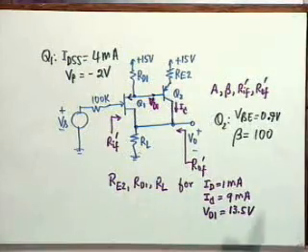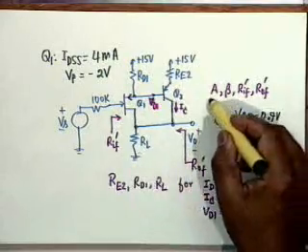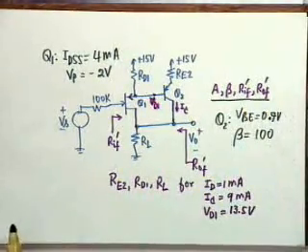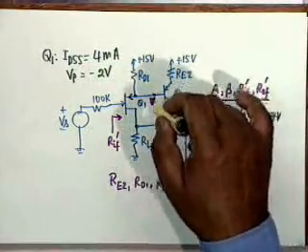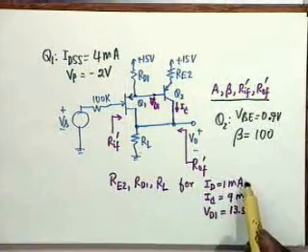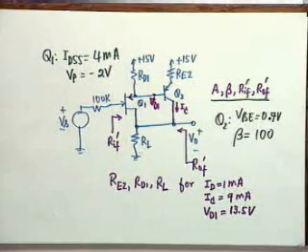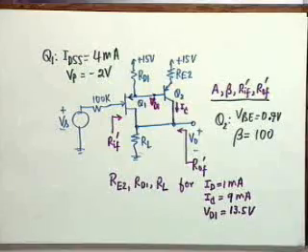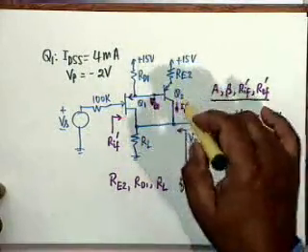Now, obviously what you have to do is, in order to find out these parameters, these are for AC analysis, you require the values of GM for the 2 transistors. And for this transistor, you also require the value of R pi 2. Alright, this is why the DC equations have to be solved first to find the DC operating condition, the Q point, then find the GMs and R pi's, and go ahead with the AC analysis. The saving grace is that this voltage is given, VD1 13.5.